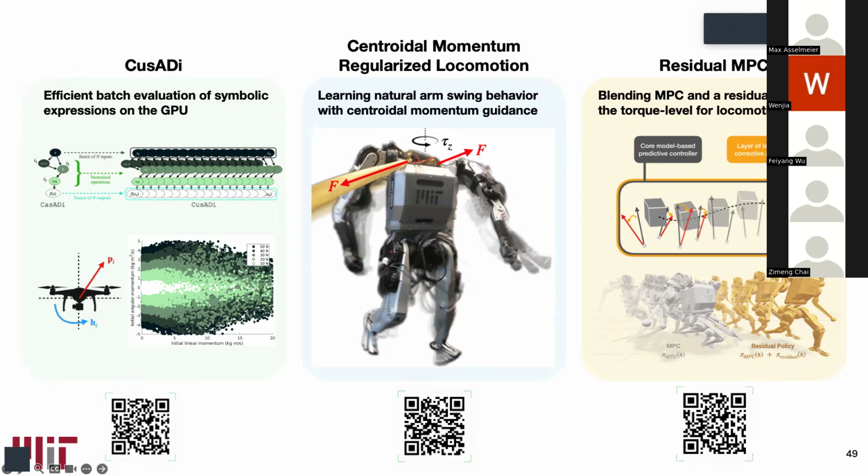Yeah. I think some directions towards that could be imitation style. If you have some offline generated trajectory, whether it's from a model-based approach or not, initializing the robot in the middle of that trajectory really helps accelerate convergence. That's kind of DeepMimic, BeyondMimic style training. I've also seen a couple of papers using what in our lab we called the God force, where you have some sort of assistive force that's unrealistic and you curriculum wean that away slowly so that it learns to perform that motion without it.